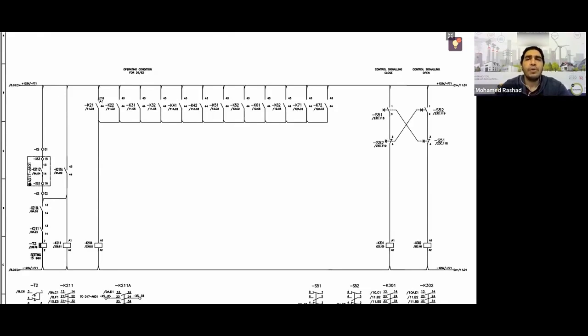The idea of double operation for the DS and ES means that if I'm operating any equipment and it is still on its way to operating, meaning it takes about 3 to 5 seconds to start up or to perform any of these actions, during this time you should not be able to give another command to any type of equipment you have in our panel.